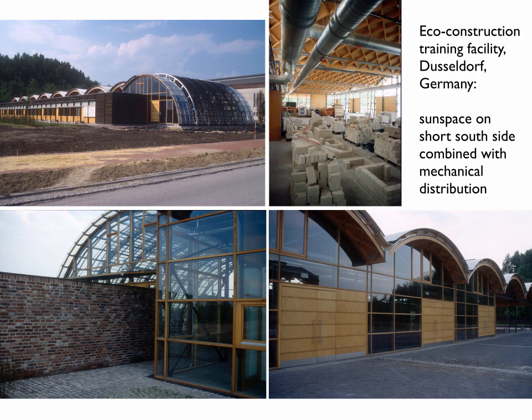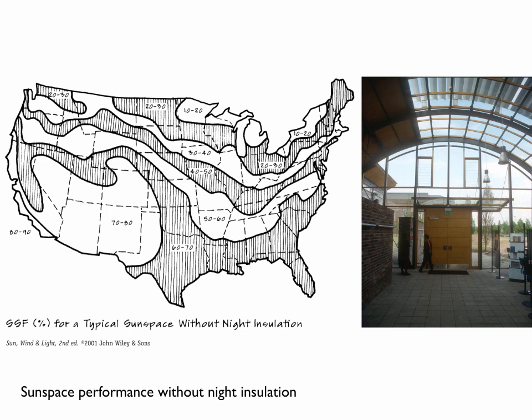And so that, if left all by itself, that room would overheat. But what they do is then take that extra heat, integrate it with the mechanical system, move it back into the shop spaces behind and into the classroom spaces that you see on the left side of the upper left image there. So the point is that you have to move the heat from the rooms that are collecting the sun over to the rooms that don't have an opportunity to collect sun.